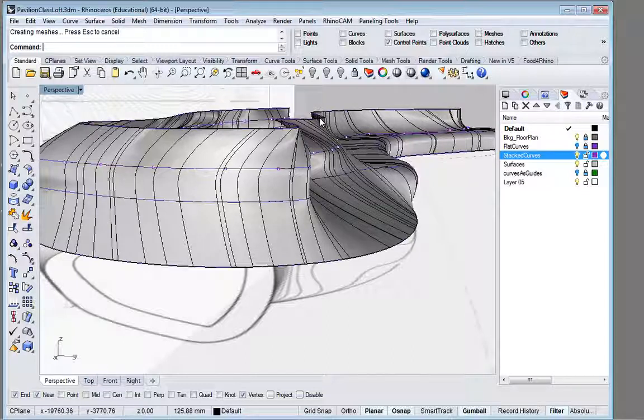Because of that tangency, getting those two surfaces to align when you do the next one, you can't really edit that bottom one, right? Okay. In that case, you should just take that one loft open. Yep, that's exactly right. And if you do record history, it will try to move the two together. But remember how in Illustrator we could have a kink or we could have a sharp curve? It would become a kink then. So if we edit it, the two wouldn't necessarily stay tangent to one another. It might actually do weird things depending on what was above or below it.